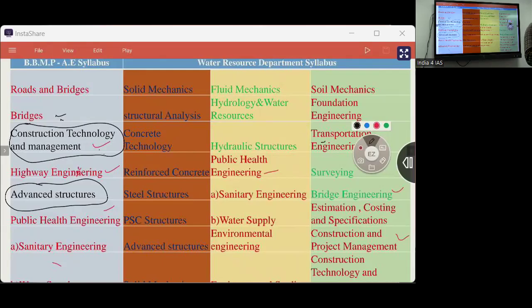So what will be the factor of safety for welding? For steel structure, 1.15. There again is a classification. These are the questions you may expect. What is the factor of safety for bolts? What is the factor of safety for welding? Tell.